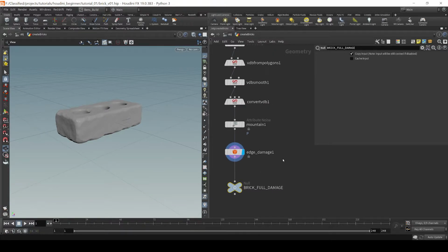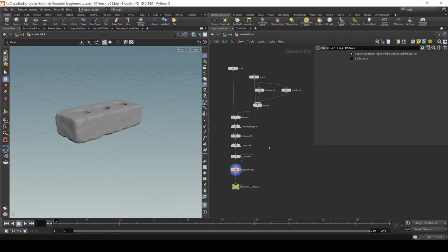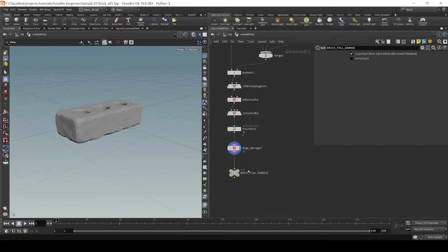Okay. And the nice thing again about Houdini is we can just kind of proceduralize this, so just change the nodes that we want to change. So what I'm going to do is select these and then hold down Alt, drag over here just to kind of duplicate the setup. And it'll take just a sec to remesh everything because it's running the node.